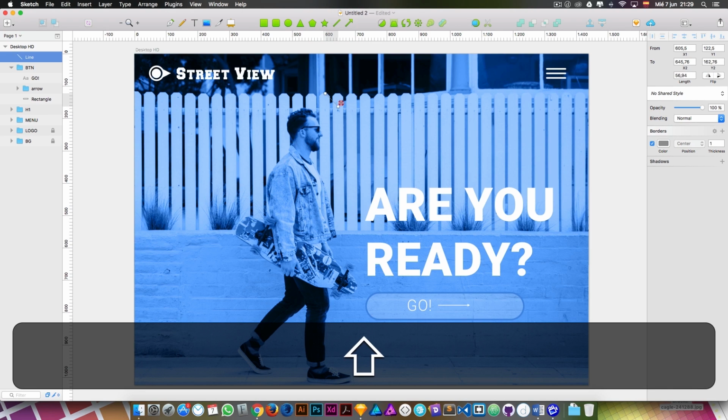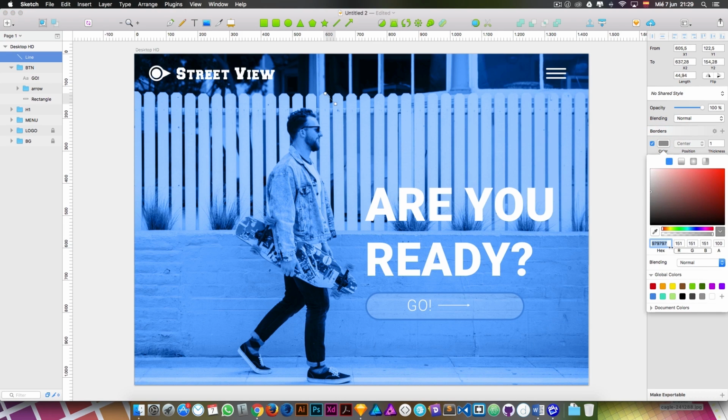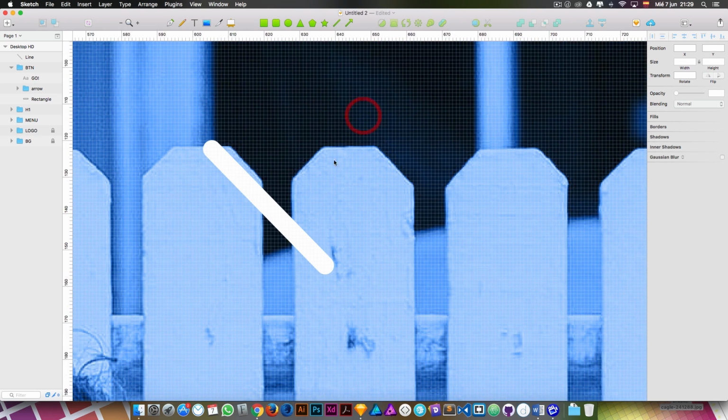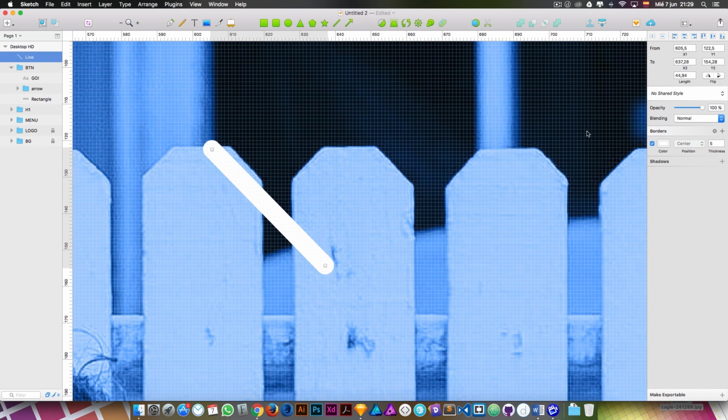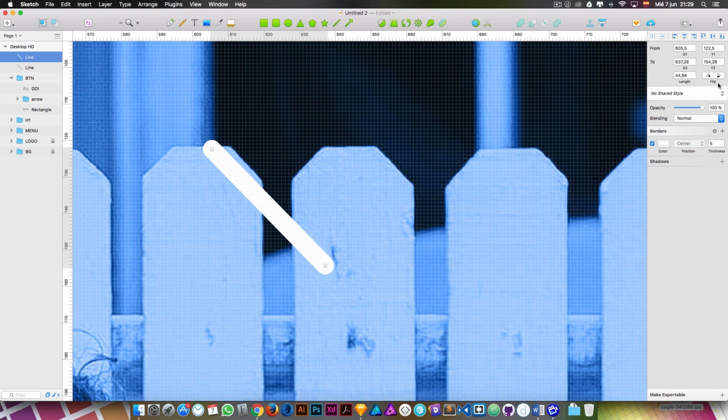So I'll make a line by holding Shift and give it an inclination of 45 degrees, a white border, a thickness of 5 and round the ends. Make the screen larger so we can work better. Now copy and paste it and flip it. Now you just need to move it and place it where you think is appropriate.